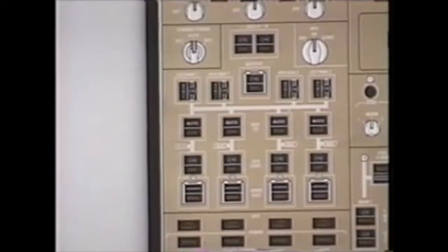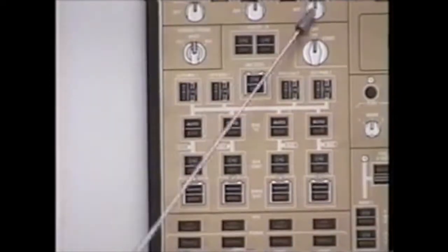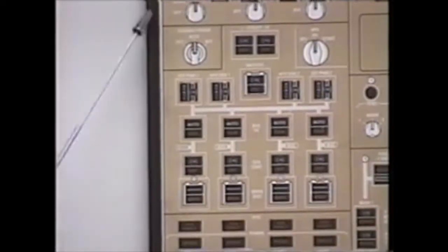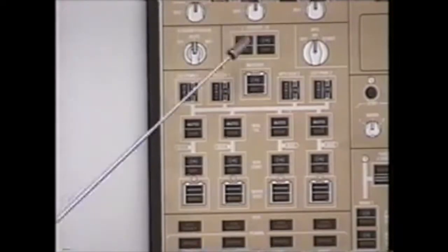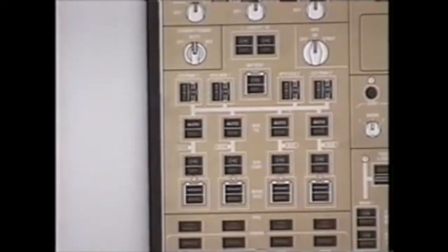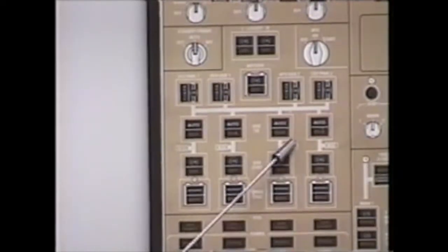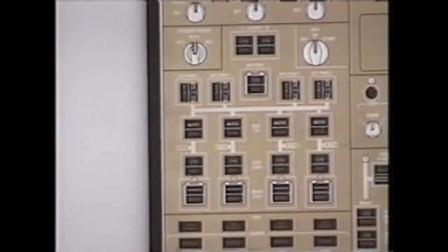Moving down and below the IRS control panel is your electrical control panel. Several switches on this panel. We'll start with the utility switches, left and right. Attached to each AC bus are 2 additional buses called galley and utility. They're attached to that respective AC bus through load controllers. If an AC bus is overloaded, it will start load shedding the galleys first, and if the power requirement is even greater, it will then shed the utility, repowering in reverse order.